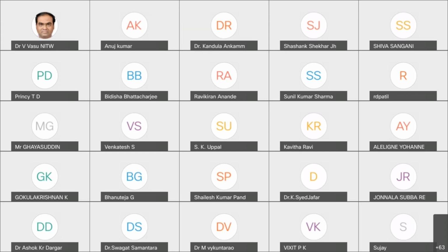So then we will discuss how we can select a particular sensor. If it cannot measure the quantity, then estimate it using a quantity that can be measured. Or you can develop a new sensor for your purpose with parameters that meet the required specifications. That is how you select the particular sensors. So sensor selection is the matching of a sensor.